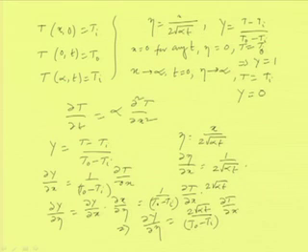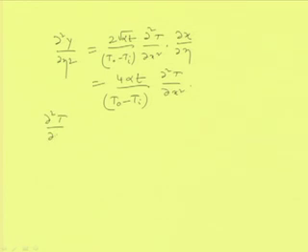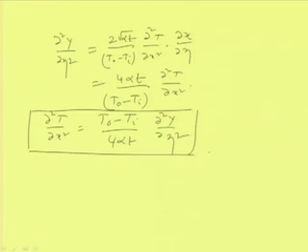Now, if we differentiate further, we get ∂²y/∂η², because we are interested in getting ∂²T/∂x². So, ∂²y/∂η² = 2√(αt)/(To − Ti) × ∂²T/∂x² × ∂x/∂η. This becomes 4αt/(To − Ti) × ∂²T/∂x². So, we can write ∂²T/∂x² = (To − Ti)/(4αt) × ∂²y/∂η². This is one conversion, where ∂²T/∂x² is converted into y and η form.